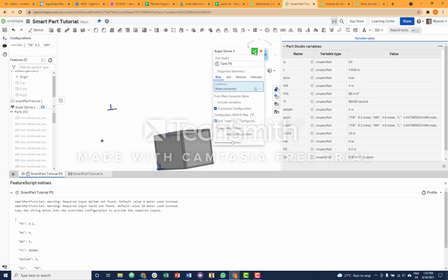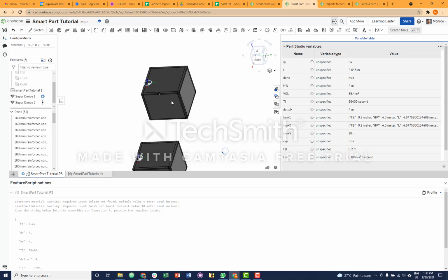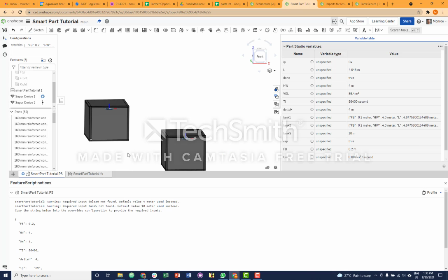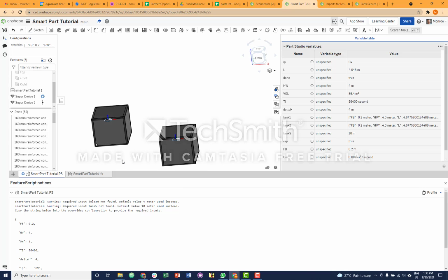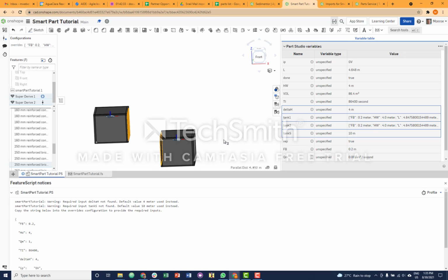And let's bring our original tank back so we can see both of them. So there they are. They're a little distance apart. They've got a vertical offset of our distance that we've specified, delta H, of 4 meters. But let's check out the space between these tanks. Okay, so we're checking between here and here. And the parallel distance is 4.8 meters. It's not 10 meters. And the reason is that the first plant is set relative to the origin, and the second plant is offset by a distance 10 meters from that origin.